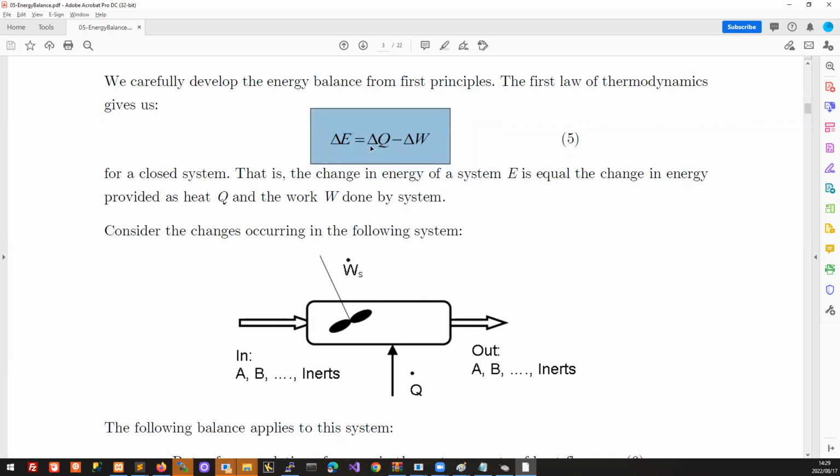So our overall energy change is the sum of those two. And it's just because the conventions are different. Work, I think the default is work done by the system, so that's energy that leaves the system, whereas the convention for Q is energy added to the system by temperature difference. So that's why the minus sign. This actually means the sum of those two. So that's our first law of thermodynamics. We can also imagine other versions of energy. For example, if our inlet stream is at a certain point and our exit stream is at a higher point, then there's an elevation difference, and there's a kind of gravity-driven energy influence. That we normally count as part of the work, part of the system.